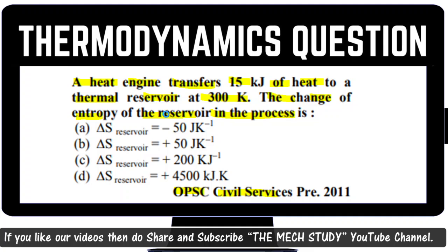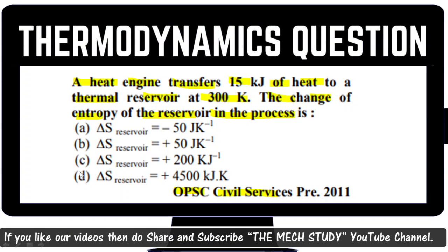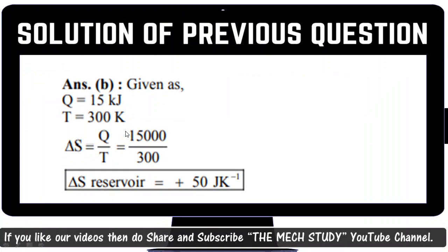If you remember the formula of entropy, delta S equals Q by T. They have already given the value of Q, and they have already given the value of T. You need to put Q in terms of joule, because all the data need to be calculated based on the unit requirement. So if you put the Q value in joules and the T value in Kelvin, you will get 15,000 divided by 300, which is 50 joule per Kelvin for the entropy of the reservoir. Option B is the right option for this question. So I hope this question is also clear.